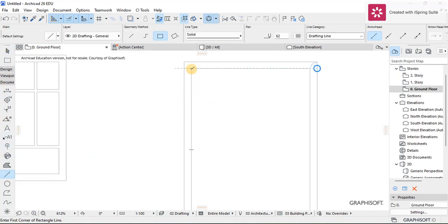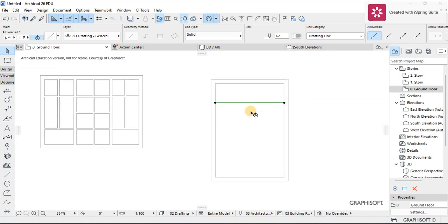Let me draw a line first here, and then I'm going to Control Shift D, a copy of that line for a distance of maybe, let's say 40. So 40 centimeters is 400 millimeters. Actually, that's too small. Let me Control Z, and let me make it another distance like 500 or 600.